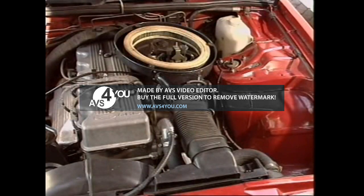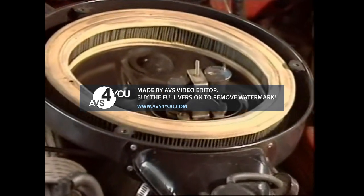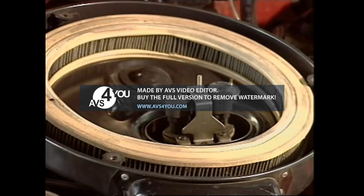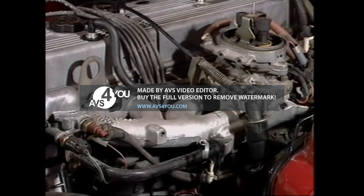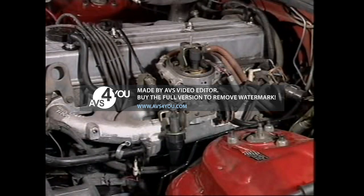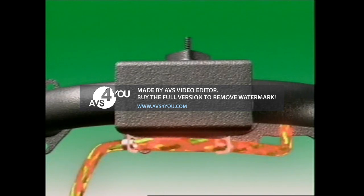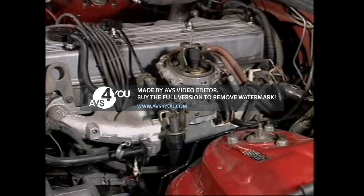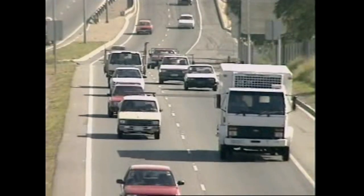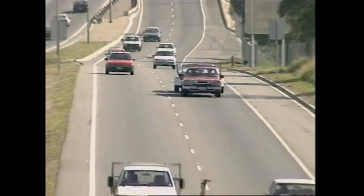In throttle body systems, the air supply is led from the air filter into the central throttle body system. Here the air mixes with the fuel from the injector or injectors, and the mixture is carried through the manifold pipes into the cylinders. Manifold design, however, is usually a compromise in order to keep the mixture vaporized. Heating the manifold by engine coolant is necessary, and the pipes tend to be smaller in cross-sectional area. This tends to limit the advantages of EFI compared to a carbureted system, but useful gains can still be achieved in power and in reduced emissions.